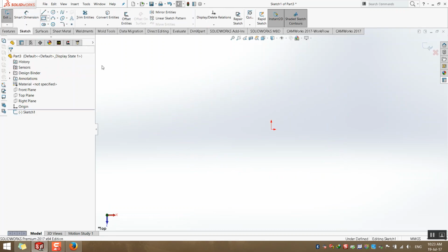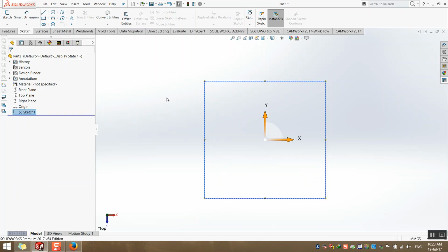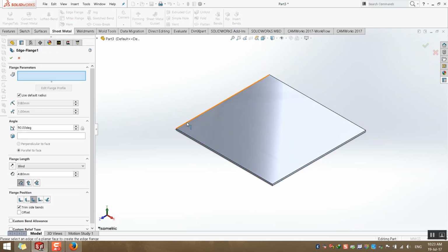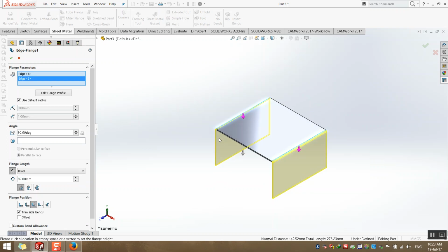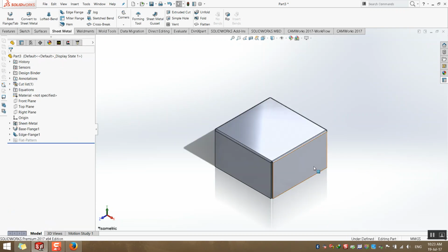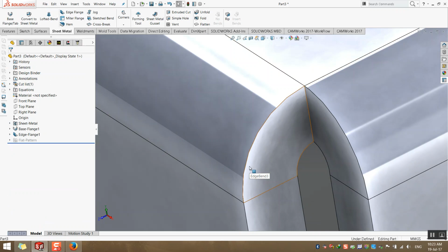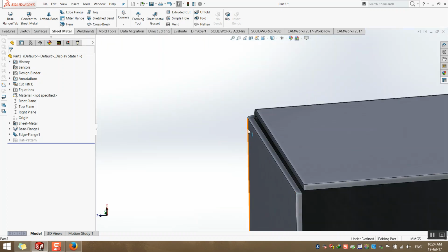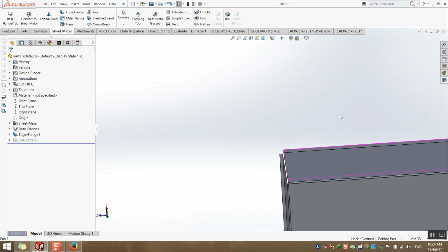Now I'll show you something like that. When you go to sheet metal, specify a thickness of 2 millimeters. Now edge flange. You just put the thickness of the material and it will automatically generate the connection for bending. This means you won't have a problem when you model a 3D sheet metal part, because you will see whether it will work on the bending machine or not, and whether we will have a problem in the bending process. According to the tools, you can also specify which tool you will use: a thin tool or a thick tool, and which radius you need.